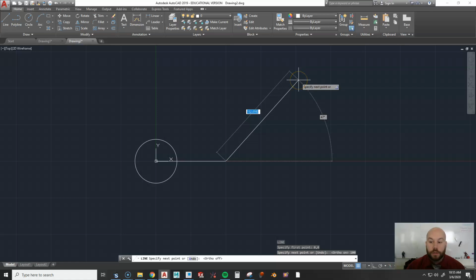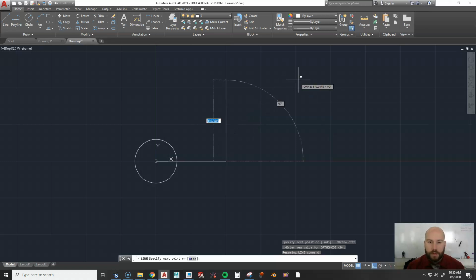All right, so I'm going to assume things. I'm going to assume that these are 100 millimeters apart, and that it's at 45 degrees. I don't like it, but I'm going to do it. So I'm going to hold shift, type at, let go of shift, and type 100 for my length. I'm going to hold shift and put in this little Pac-Man symbol, and you can actually see it next to the 47 right now. Okay, I call it Pac-Man. I know it's a less than sign. I'm going to let go of shift, type 45 degrees, and hit enter.